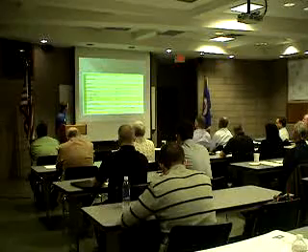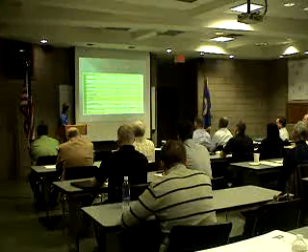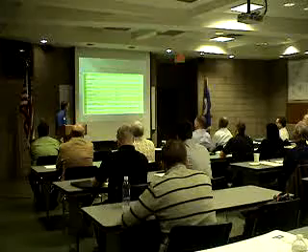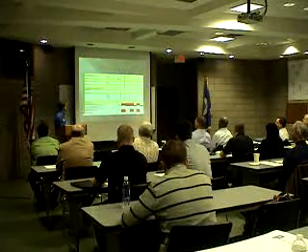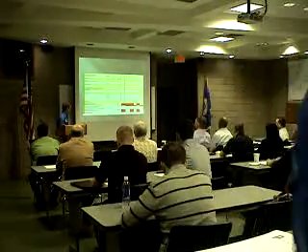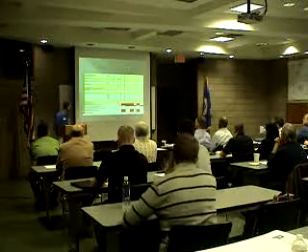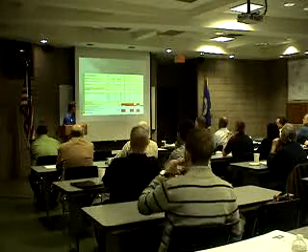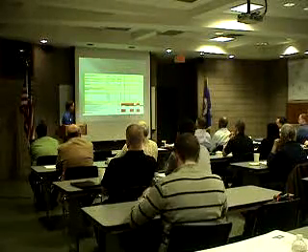The general lighting load, largest on the lighting load, along with track lighting, sign and outline lighting, parking lot, and then down from that is the motors. Motors we took from 430, sized all the motors, and then took the largest by 0.25, and we came out with the main panel 500 amp, receptacle panel, like I said, 100, and the lighting was 200.